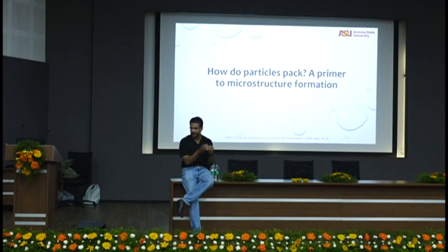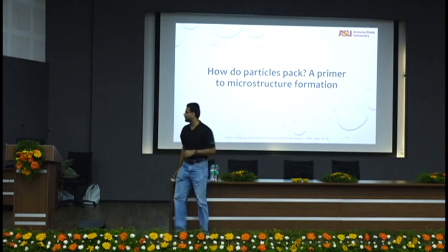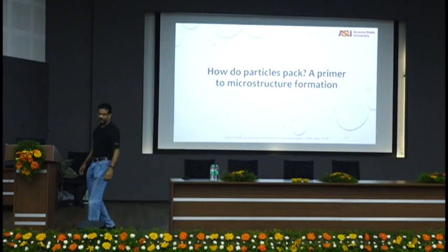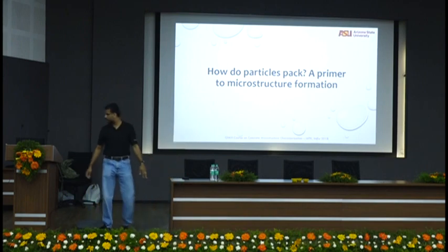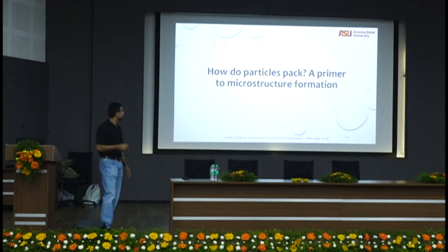If you want to think of only cement paste. If you want to think of mortars, you can think of how all the sand grains packed together and in between there is a paste. If you want to think of concrete, you can think of how all the coarse aggregates fit together and how everything else is in between. So whatever I'm going to talk about now applies to any length scale in concrete that you want to think of. But what we're going to do is some of the basic theory and the basic understanding of how particles pack, which results in the microstructure formation.